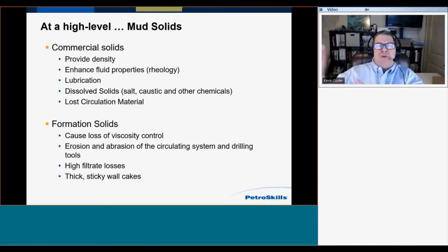And so those are two high-level categories. I'm going to spend some time here in just a minute diving more into those and talking about the different characteristics that we see. But generally, we talk about commercial solids. Again, somebody is paying to put those solids into a fluid. And we talk about formation solids, solids that are generated from the wellbore. We drill a formation. The solids are drilled up by our drill bit, and they are incorporated, hopefully not for long, into our fluid system, and then we remove them at the surface.